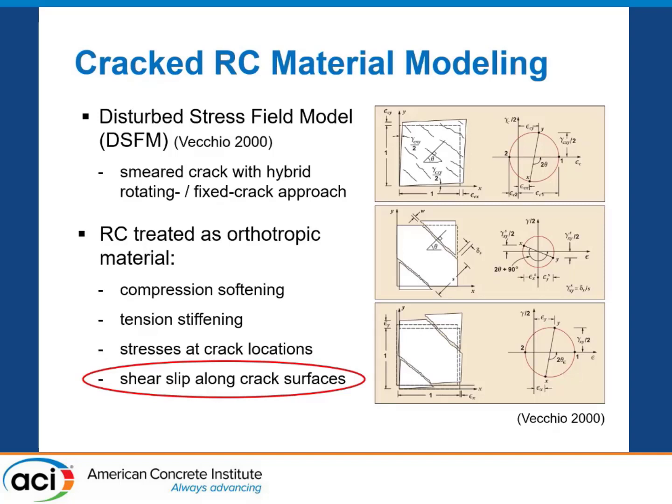In terms of material modeling, it employs the disturbed stress field model, which is an extension of modified compression field theory. So this is a smeared crack modeling approach, and it's something of a hybrid rotating fixed smeared crack model. Inherent to it, without really a whole lot of modeling specification, it accounts for compression softening, tension stiffening, and a key feature is really what it does at crack surfaces.